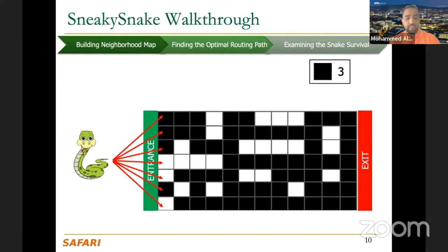So how do we solve it? It's very similar to the single net routing problem. In each row, you detect how many steps you can go further. So you find here 0 steps because you start with an obstacle or a module, then you cannot pass. Here you can move 4 steps forward because your goal is always to go from left to right. So you want to go as far as possible in each row. That is a greedy choice to get the shortest path. Because if there are no obstacles at all, then you just walk in a single row and that's it. You solve the problem.